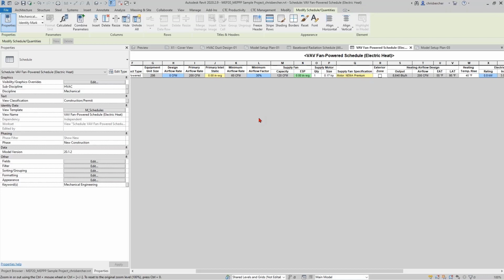You may want to go back and edit the family again and link some of those parameter values up to the connectors to make sure that you are actually propagating the appropriate information throughout the model when appropriate. So there may be some extra work to do, and it's not just processing of a bunch of settings.